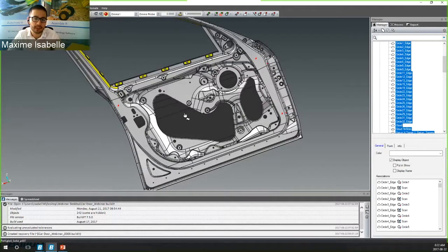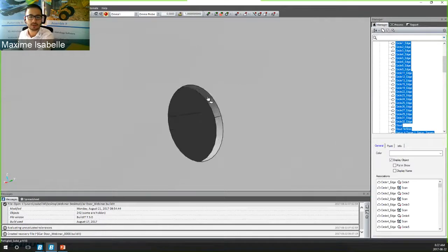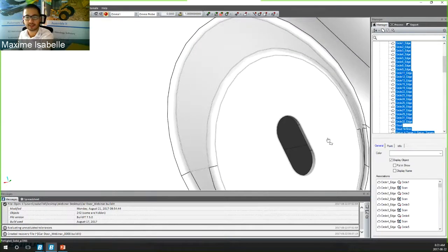Okay, so this is an example where the part is made of sheet metal, and this poses a particular challenge when it comes to hole positioning. When you want to inspect the position of a hole, it becomes very difficult for a scanner to obtain all of the necessary points on that very thin cylinder or that thin slot right here.